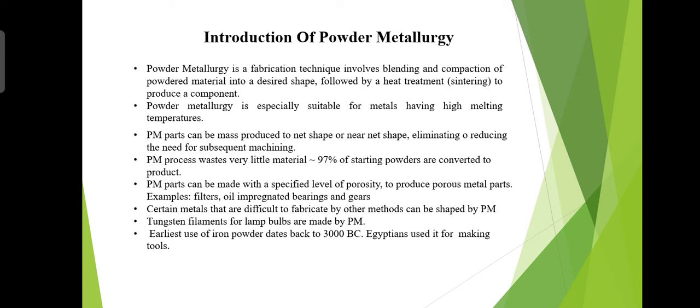Varying the temperature or pressure during fabrication can also affect material properties. Parts can be forged to final or almost final shape, eliminating costly machining. So, powder metallurgy is useful in making parts that have irregular curves or that are hard to machine.